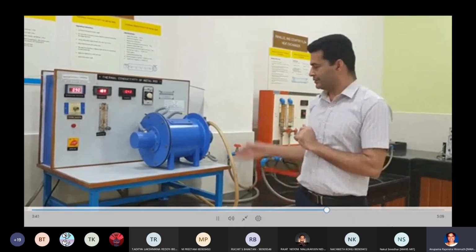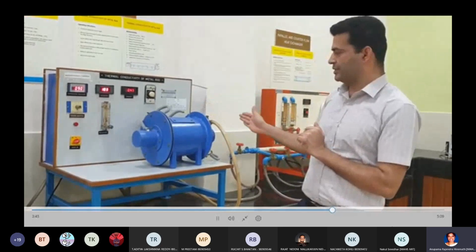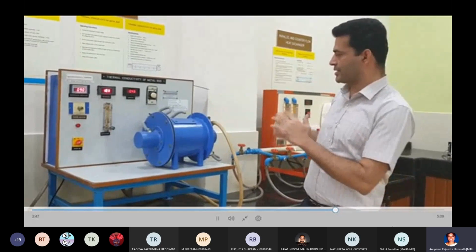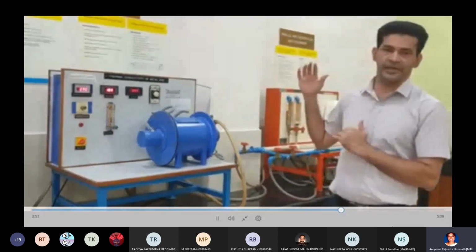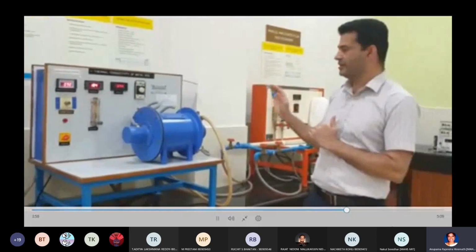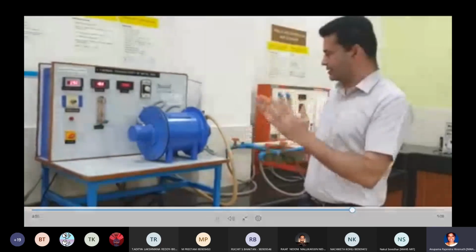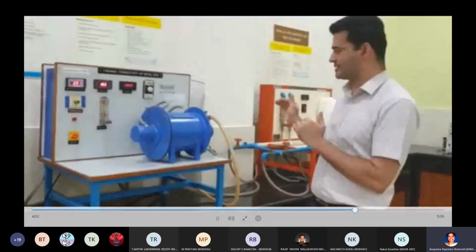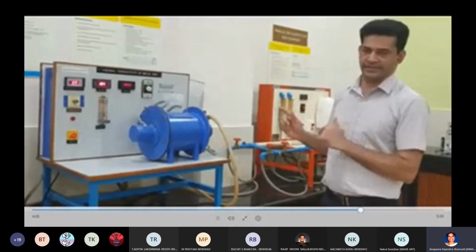That heat is actually coming through conduction along the rod, because the radial or peripheral heat transfer is prevented by providing a good amount of insulation there. So we make a 1D heat conduction assumption here, and we can plot the temperature versus distance graph, and from that graph we can obtain dT by dx.